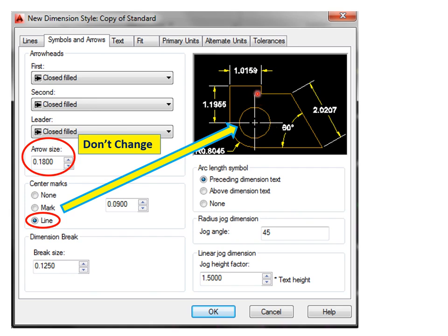But if you want AutoCAD to auto-generate center marks with extension lines, anytime you add a radius or diameter dimension, then click this one. So this is optional. Leave it up to you which way you want to go. Some of you will prefer to have it off and just draw your own green center lines. Others will prefer to auto-generate those lines when you use the radius or diameter command. And here are some more options, things that you can change, but again, you'll never have to change these. Typically, you just leave them alone and it'll be set by your company standards.